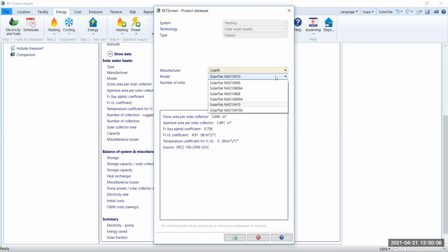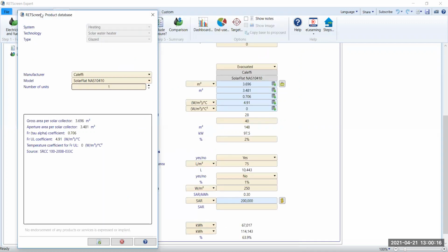Doctor, when you said unglazed, that's used like in swimming pools, what do you mean by that? I mean that in swimming pools, if you go back to the chapter 6 presentations, you'll find that there are some cases where you use solar collectors that are not covered with glass. Convection losses are high. Accordingly, you cannot heat the water to a high temperature.